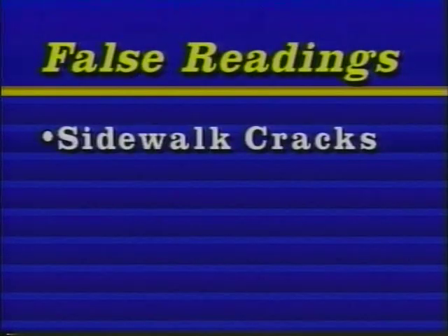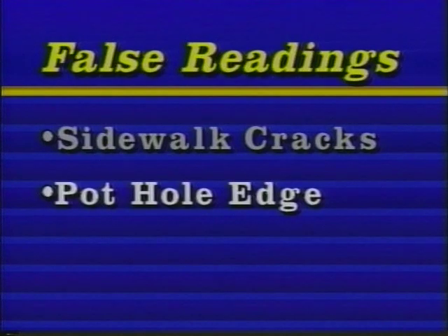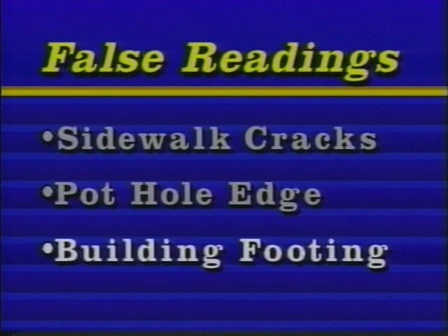As with the railroad track, the sound waves hitting this hard surface may be some distance from you and traveling sideways along the surface in contact with the microphone. If you're going to hear a thump, it must be a louder sound than the background noise, or you won't be able to distinguish it from the rest. Never set a ground contact microphone by a crack or in a sidewalk or at the edge of a pothole or the footing of a building. If the hard surface material is not in firm contact with the soil, it could vibrate and produce a loud sound, even though the thump is striking some other portion of the hard surface.